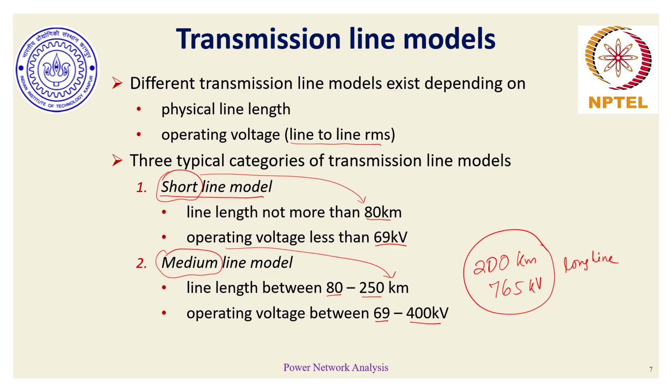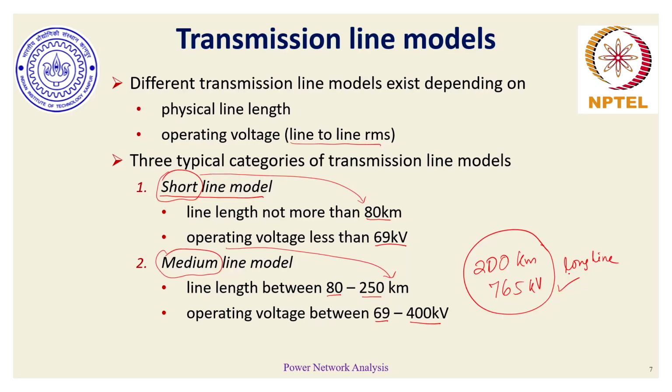Again, as power engineers, we do understand and consider the aspect of trade-off. If the line length is substantially small, let's say a few 50 kilometers or hundreds of kilometers, then unnecessarily modeling this particular line as a long line might result in taking more time.